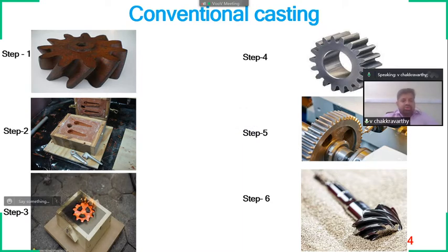Okay, because with tough to machine materials, when we are trying to machine them, the tool will obviously undergo wear very quickly, because the material has very poor thermal conductivity, and the tool will have some kind of build-up edge, which is like the material will recast and get deposited on the tool itself, and it will further promote the tool wear. So in order to